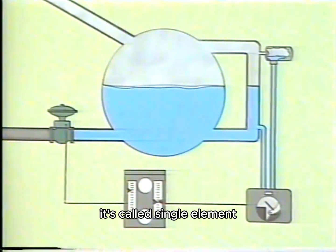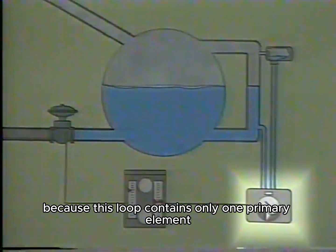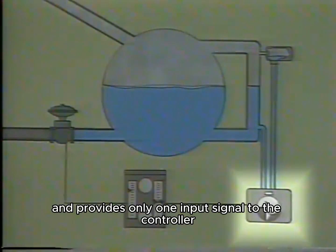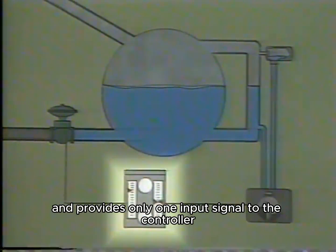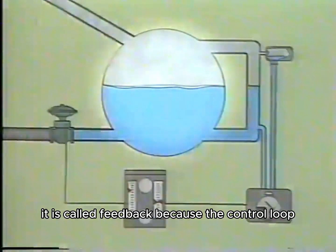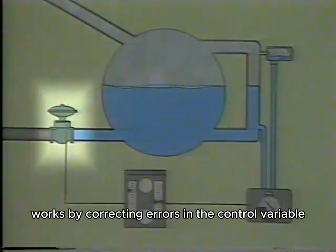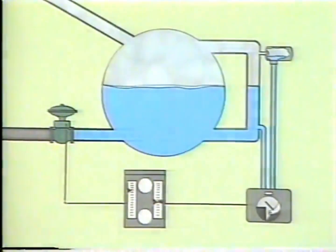It's called single element because this loop contains only one primary element, which is combined with the measuring element in this transmitter, and provides only one input signal to the controller. It is called feedback because the control loop works by correcting errors in the controlled variable after they occur.